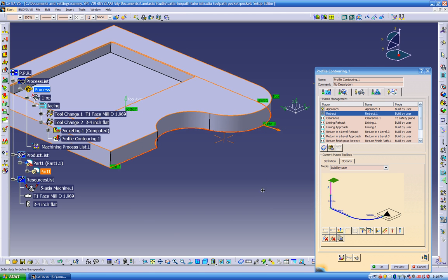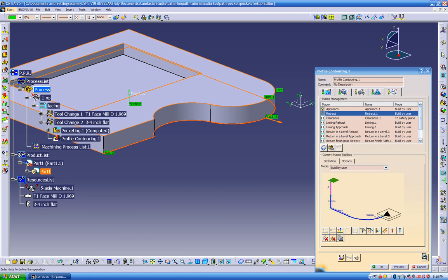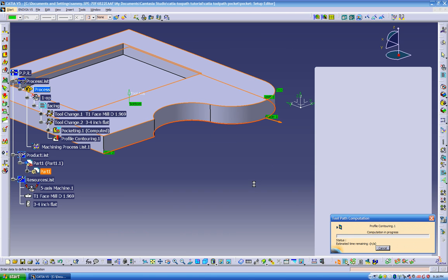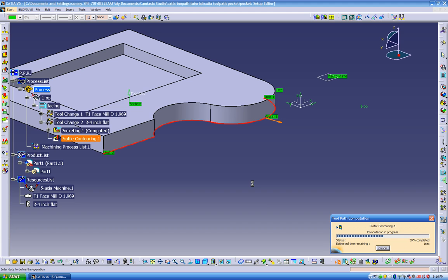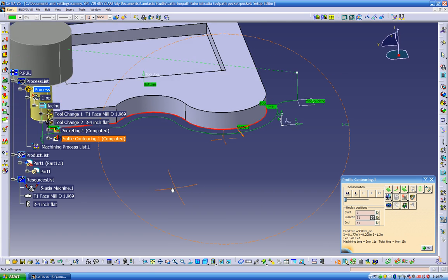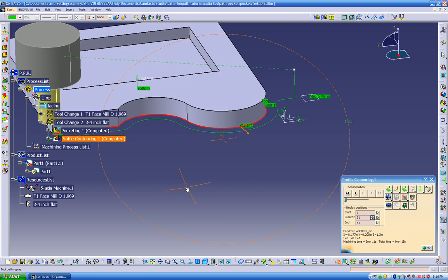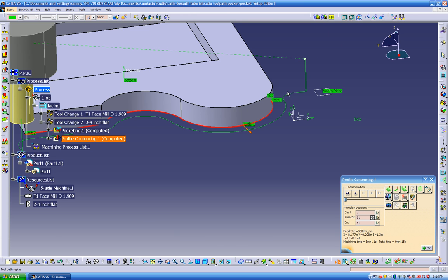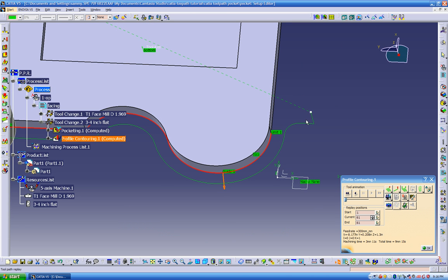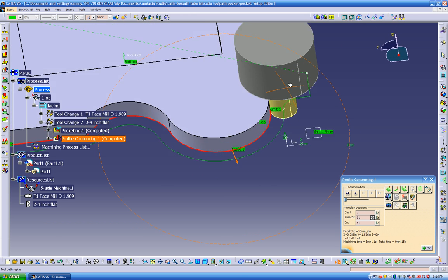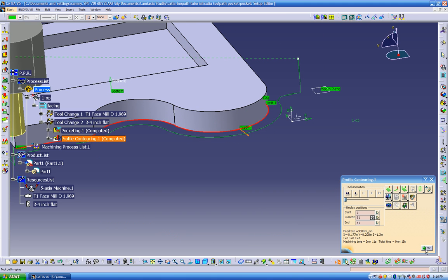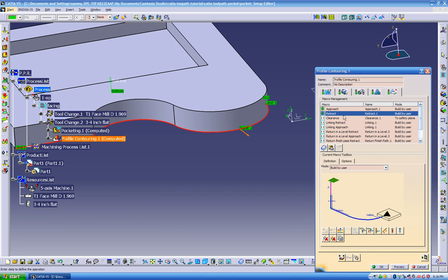select the plane, and now I can do a toolpath replay. So our tool, as you see, starts outside, leads in very nicely, comes into the part right here. See, if you don't use the lead in options, let's go back over here and we can delete these macros that we just selected. So just click on remove all motions.